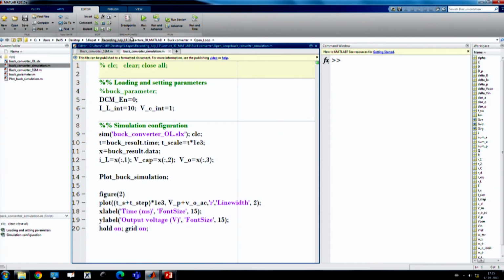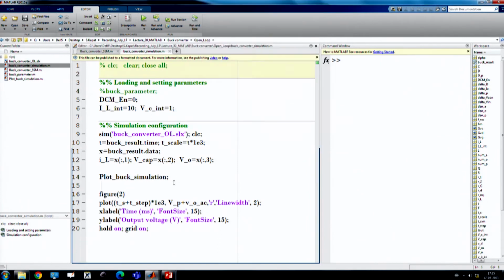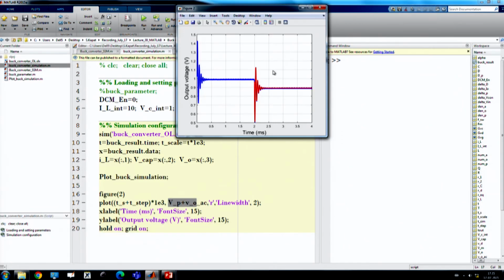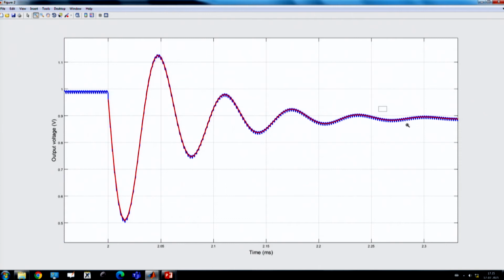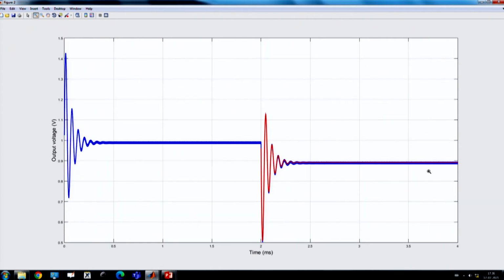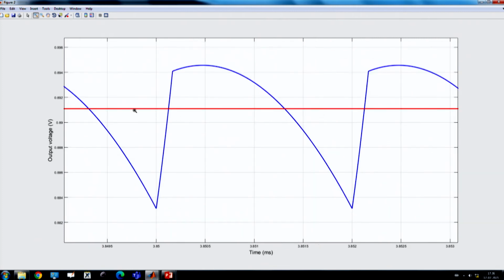That means, now if we run the actual switch simulation, and I have explained step by step everything. So, where we have to capture the AC model, then we have to add with the DC offset. So, everything you see, I am taking the V practical that I have explained. Now, this is the simulation. The red color trace is the waveform obtained from the AC small signal model, and you can see, if you keep on zooming, that it represents the average voltage correctly. That means, if you take the average, it is more or less capturing the average voltage, it is going almost through the average value. Okay.